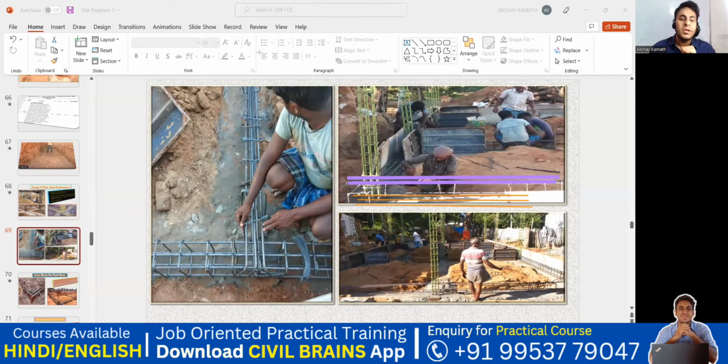Now you tell me what was the reinforcement written here. You can see 3 bars, isn't it? 1, 2, and 3. So 3 in the top, and in the bottom also there is 3. I'll take this as 1. There's one more here and one more on the side. So 3. Now you got it. So in the drawing, if it is written 12 of 3 at the top, 12 of 3 in the bottom, you're supposed to provide that. If it is written 12 of 2 in the top and 12 of 3 in the bottom, at the top you provide 2 bar and at the bottom you provide 3 bar. Done? Very simple.